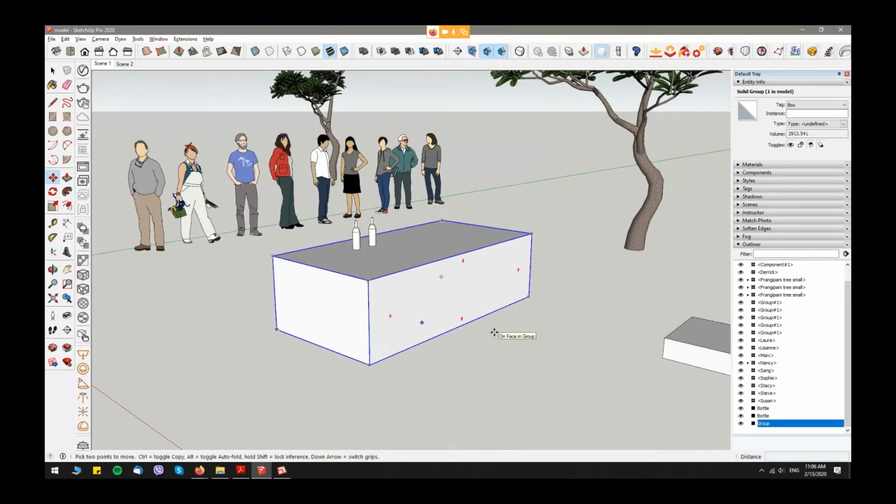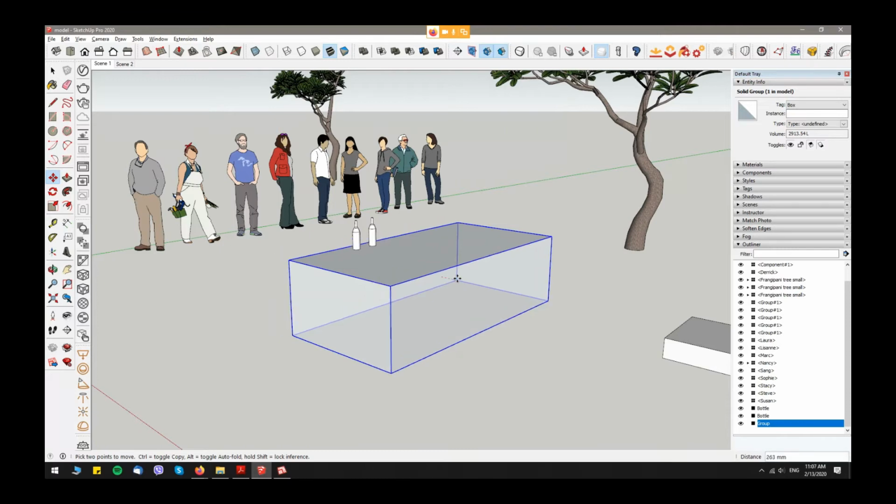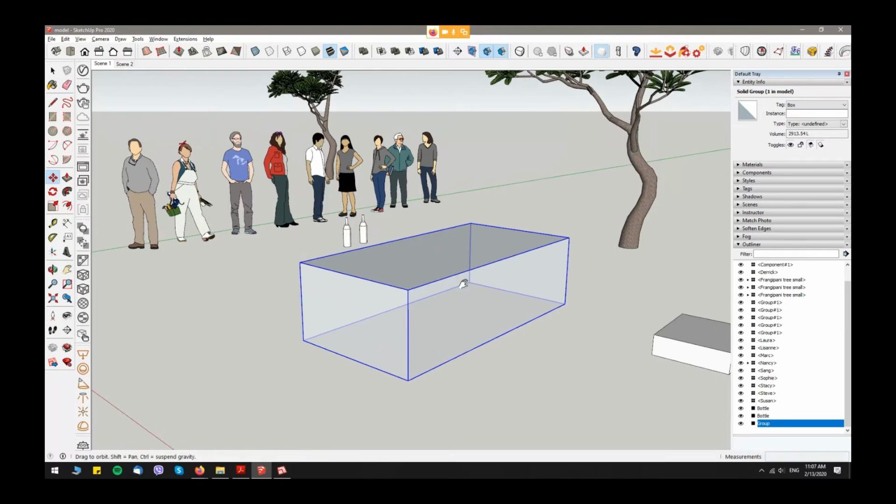The most exciting thing is background points. When I take these points on the backside of my view, I can select this corner, and my object is transparent. Now I can see everything, and I can snap my object very easily.